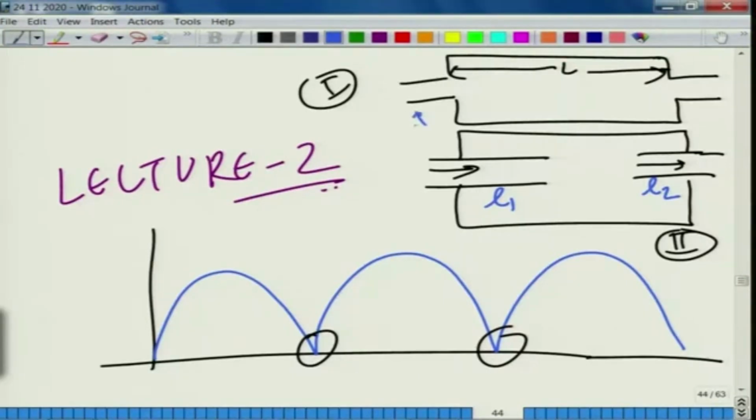So, this is the inlet, this is the outlet, and when you have these extensions, it is possible that we can create resonances by suitable insertion, by tuning the lengths. All this while we are assuming only planar waves to propagate, here and also in the chamber.